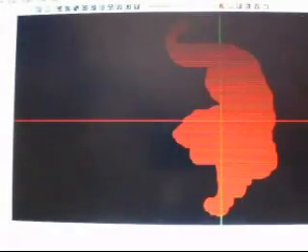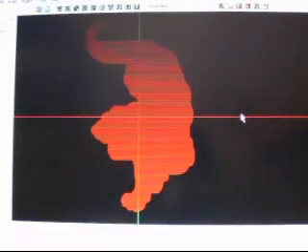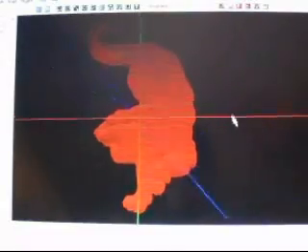And now I don't have anything on that layer. It's done computing. I don't have anything on this layer anymore. All the information is on my new layer, and it's all been converted to polylines. So let me zoom out to fit. Zoom to fit, and you will see. Let's just take an isometric view of this.